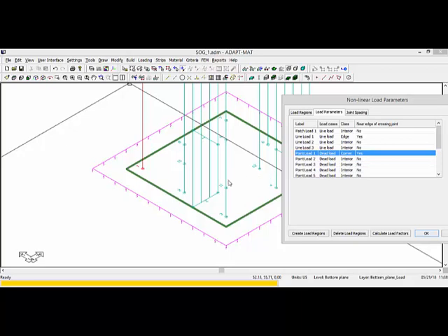And yes, we do want to transfer that. I'll also look at, let's say, number 2, which is an edge load. So we'll call this an edge load. Yes, we want to transfer a portion of that magnitude across the joint, and we would go through the loads and systematically determine which loads we want to consider as being transferred over the joint.